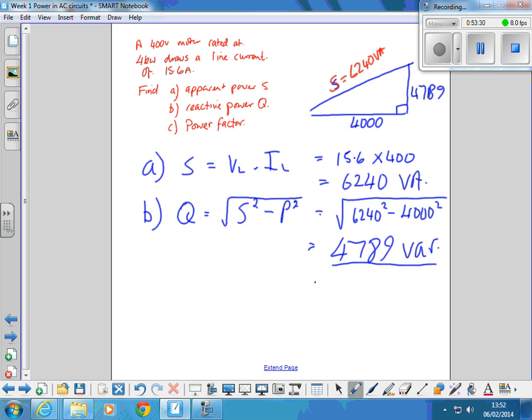On real power systems, we're quite often going to be talking about kVA, kVAR, and kilowatts. And if you've got all of those three quantities in K, you can just put the numbers in and the answers in K. So if you've got the power in kilowatts and S in kVA, you can just put the numbers in and you'll come out with Q in kVAr.